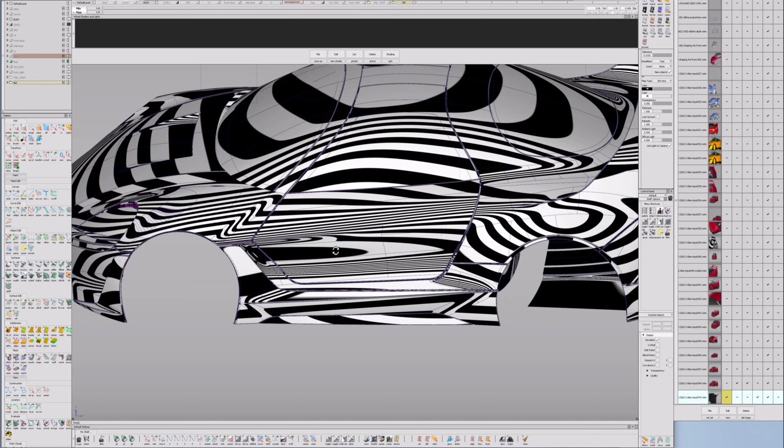If it goes a little bit further, like maybe a 1-to-1 scale model, then you should be more careful, because it goes to a milling machine, and a milling machine is really sensitive to bad surfaces where CVs are twisting and you have crazy sections.